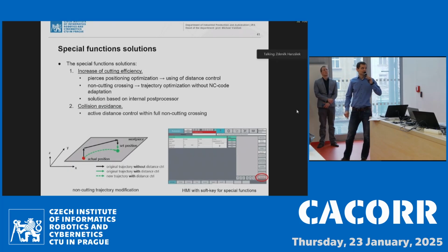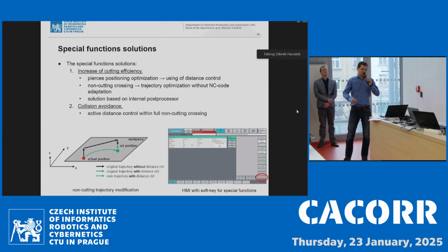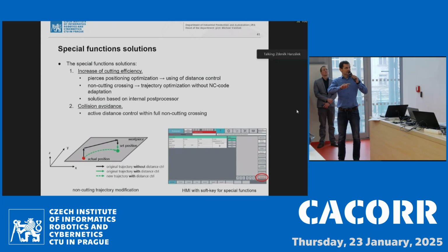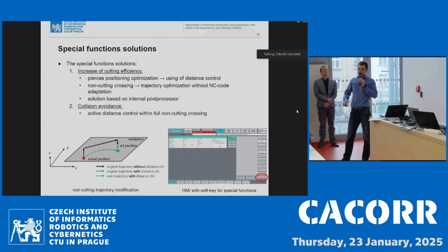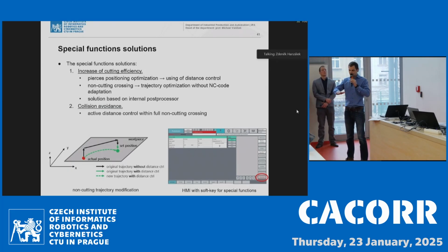So we modified this procedure as follows. We still have distance control on and move only in the XY plane, and the distance control enables the Z-axis positioning. You can modify the gradient of this movement for the user. We selected a 10 scale grade, and if you select 0, you copy just the original path, with the difference that the distance control is still on. It means it still checks any obstacles which are on the metal sheet.